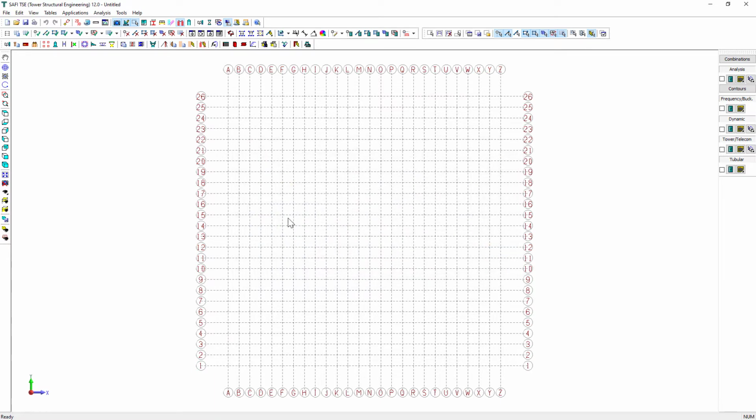Now, we are ready to start creating the tower. The first step will be to locate the tower. The first geometrical element that must be defined is the column. This column will then be used as a reference to create beams, diaphragms, and rigid connections. The column is located by its center line. The dimensions of the column are not defined in this step.